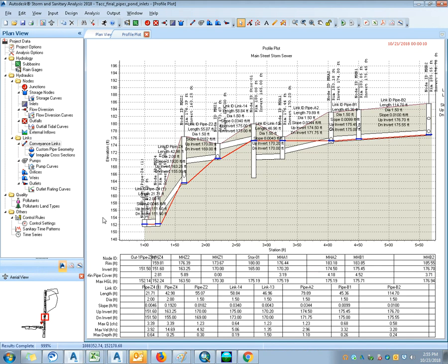What's also interesting is that a lot of it has to do with our local hydrology, but they don't require HGL lines to be calculated. No, I think you do trigger it sometimes. I think we've asked for them in the past. I also worked in development engineering, and I'm not sure if they still do, but in the past, if we saw a bad spot, we would ask for a hydraulic grade line. But maybe not anymore. We really want to know. We're not doing just the subdivision design. We're at the receiving end of all their subdivision designs. We really want to know what happens in a big storm.